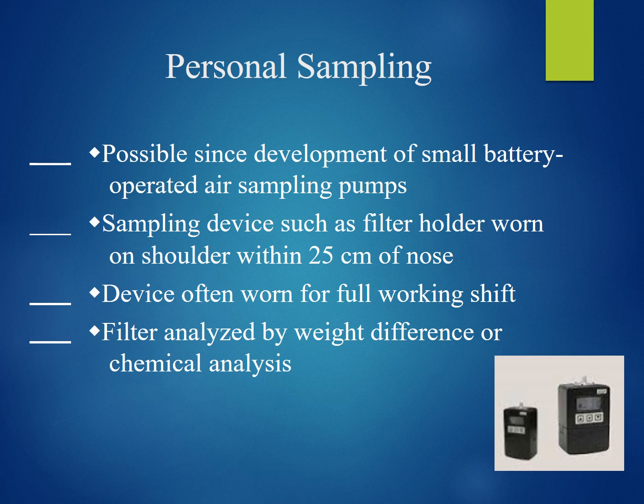Personal sampling is key to accurately measuring a worker's potential exposure. Employees are not static and do not stand in one location. As a result, area sampling is not representative of worker exposure, and the results of area sampling should not be compared directly to an OEL. Historically, area sampling was preferred to personal sampling due to pumps being big and bulky. However, today, we have very small pumps that are lightweight.